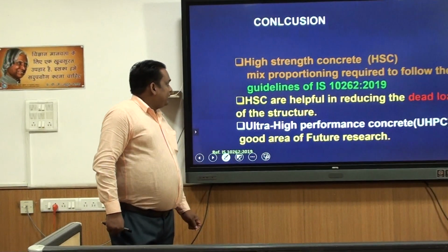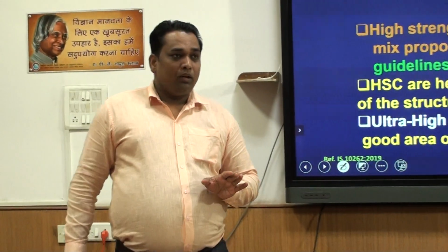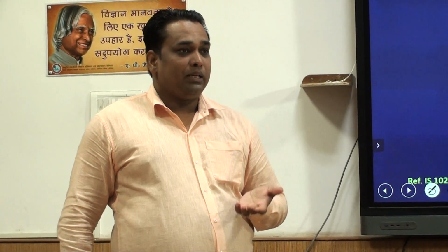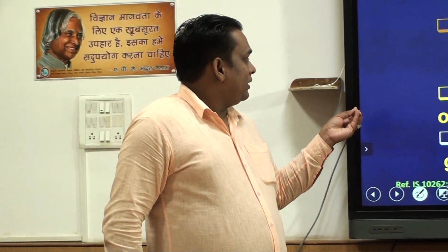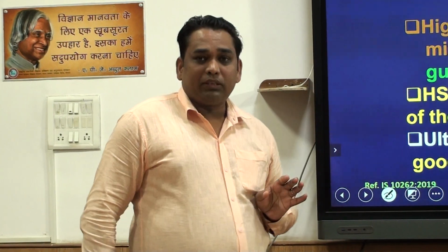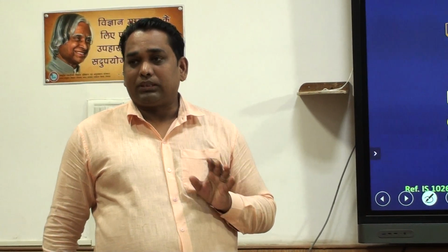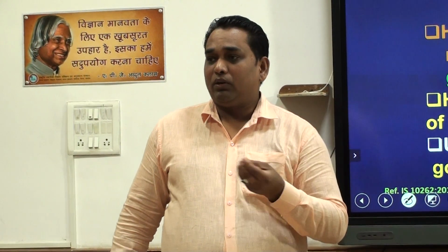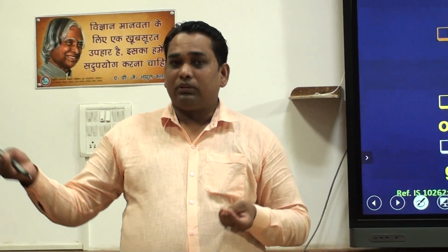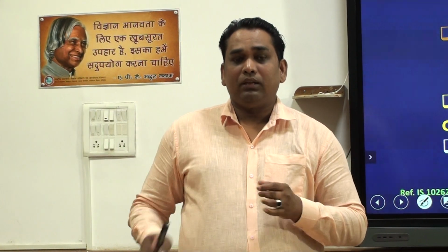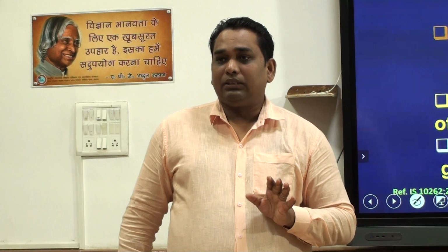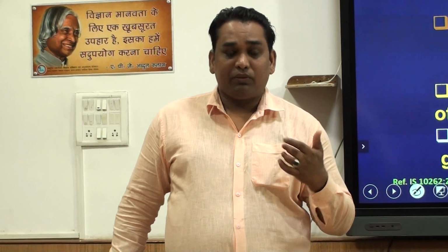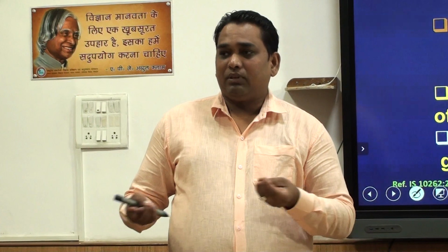So, conclusion: after this session you have some idea about high strength concrete, and we can understand that high strength concrete is very helpful in reducing the dead load of the structure. So dead load means permanent load. Permanent load is called dead load, like columns, beams, slabs, foundation. These are permanent structures in every civil engineering structure, so these come under dead loads. So if we use high strength concrete, the size will be reduced, and automatically the dead load will be reduced.